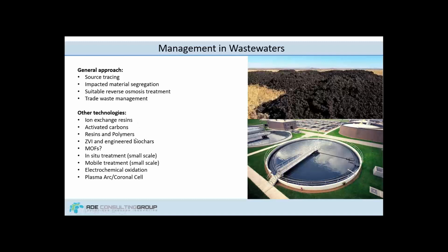There are also a number, just while I'm on this slide, a number of other solid resins and polymers that are used, typically in oil and gas. And I guess their function is that they have a smaller footprint, and the plants can be smaller than a loose bed resin. So a number of providers here, a number of service providers with unique technologies that all have their own benefits. There are some that I didn't mention here, like zero valent iron, metal organic frameworks, and then also there's some work being done in electrochemical oxidation.